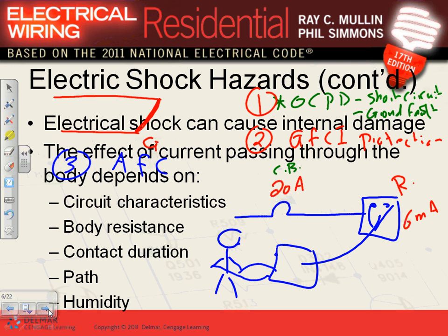Your third protection in the same circuit that you're looking at, guys, is arc fault circuit interrupter. If the equipment starts arcing and sparking, you plug in things here and your equipment starts arcing and sparking. How would equipment arc? If you have loose connections, it's not a short circuit, it's just not connected right, it starts arcing. When you arc, guys, you create obviously fire and heat. Heat creates fire, and fire burns buildings. So the arc fault circuit interrupter is supposed to protect you from fires, not from short circuit. Okay, so here's the third protection that you're going to have.